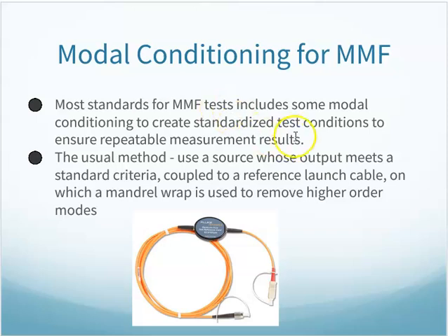All right, the reference cable we're going to end up using is this guy right here. We're dealing with multi-mode fiber, so we need to do some conditioning. If you remember earlier when we talked about fiber, you have the low and high order modes coming through. If I loop that around a bunch of bends or circles, it tends to even it out. The low order light modes are the ones that end up making it through. The ones that are bouncing up and down get filtered out, if you will.